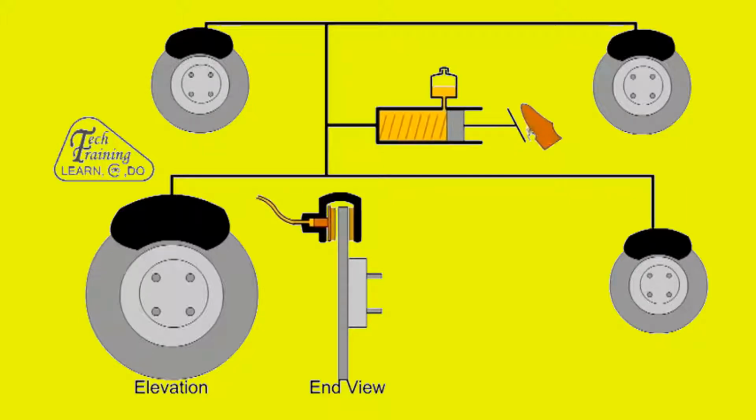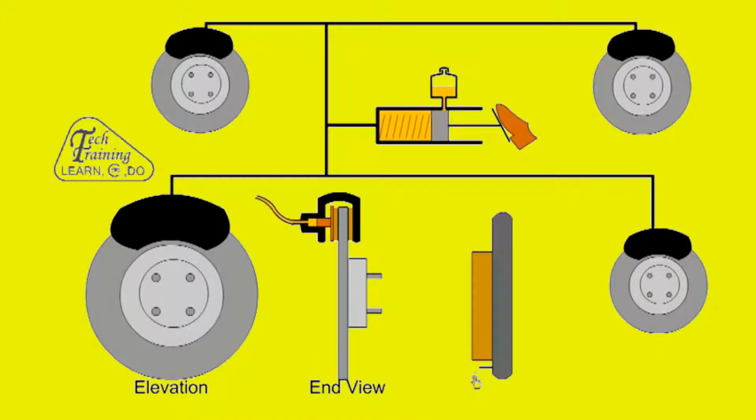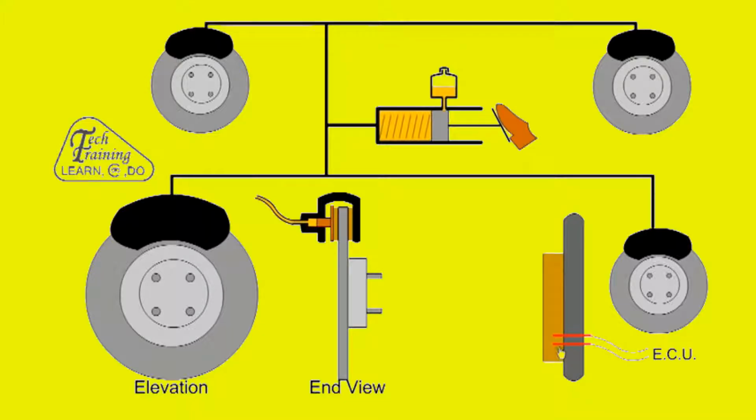This is a single piston floating caliper, self-adjusting and self-centering, which is used in most cars. Cooling air is channeled over the brakes to assist with heat dissipation. Periodically, the pads will require changing. Some pads have a metal wear indicator which makes a squealing noise when it contacts the disc. Other cars have wires embedded in the pad. When the pad wears out, the rotor completes the electrical circuit and activates a warning light. In the past, the friction material was secured to the shoe with rivets, but now a bonding adhesive is used.